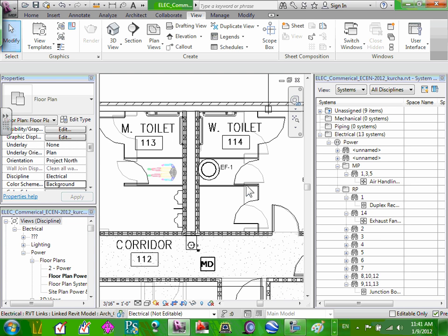That's typical, guys, in a commercial building. They have one fan that works for both male and female bathrooms, sucking the air out. And the nicer thing is, instead of you walking in and turning it on, the occupancy sensor has a contact that interfaces with the control circuit of the exhaust fan. When the occupancy sensor picks up and turns the light on in either bathroom, at the same time the exhaust fan will start. We're not going to show this in terms of power. This will be a keynote. Cool. Any questions, guys, about the exhaust fan?